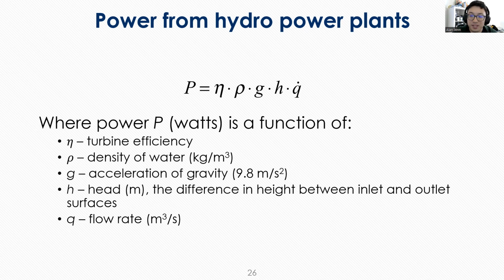That's where your flow rate comes into play, so you divide by seconds here, but otherwise your mass is the density of water times the volume from the flow rate, in meters cubed. So you have your mass M times g, 9.8, times h. An easy way to remember it is that you can always derive back to power from the potential energy equation.